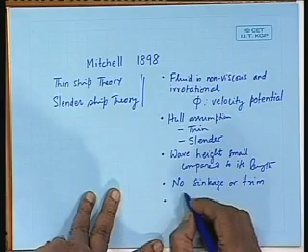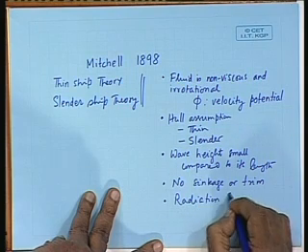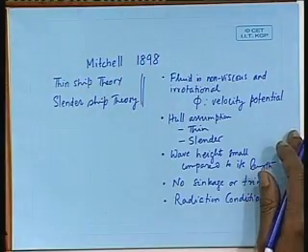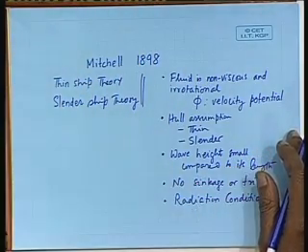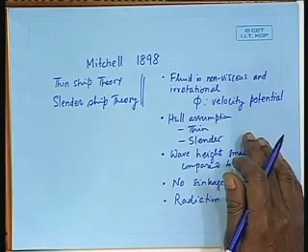And finally, the so called radiation condition, which means the waves travel only back, waves exist only in one half of the horizontal plane, that is aft of the ship, and they can travel into infinity in that direction, but there will be no wave in the forward side. So, with these assumptions, it was again Havelock who showed that you could represent a pressure point by what he called a source.